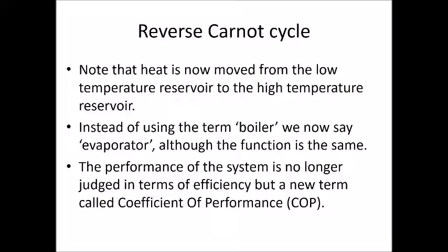So we don't talk about something called efficiency anymore, because you'd have more than 100% efficiency, and then that would really kind of confuse you. So we use this term called coefficient of performance. And what coefficient of performance is telling us is how much thermal energy is being moved per unit of work energy that's being put in.